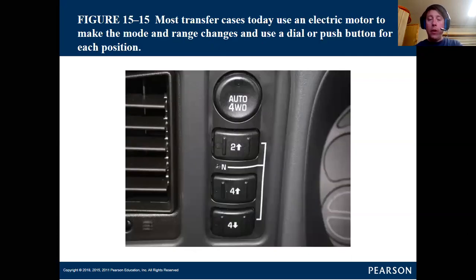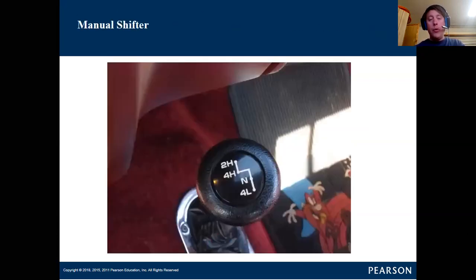You might think that's not a big deal, but it is. You have a parasitic loss in fuel economy when you're forcing the engine to drive a vehicle down the road, and then in reverse, the front wheels are being parasitically drained of energy. They have to push not only the tire, but also the front axle, and they have to push the front drive shaft for no reason. It is a horsepower eater.